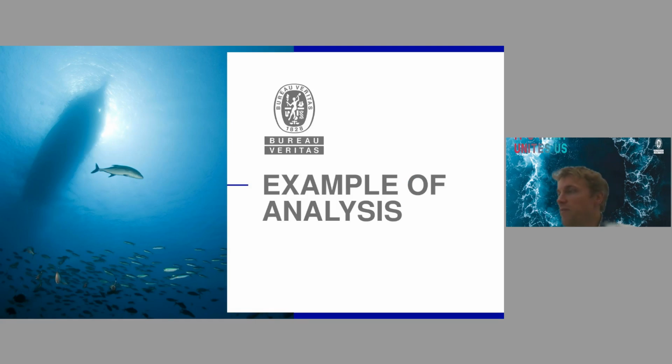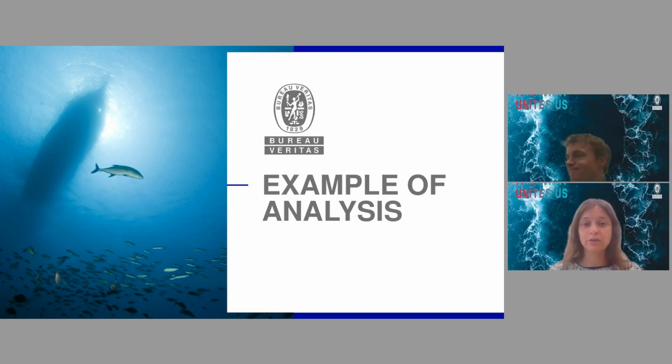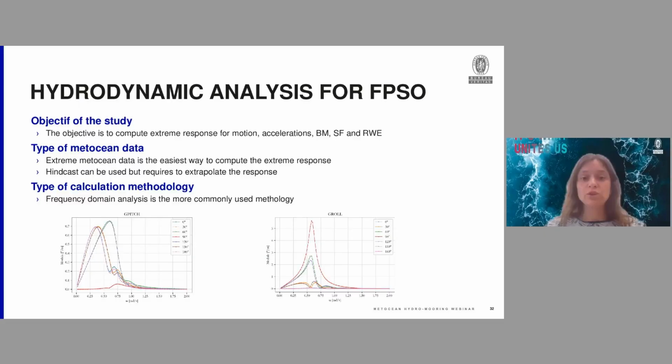And I will give back the floor to Claire-Julie to provide some examples of analysis. Thank you, Guillaume. So to sum up, some examples of really simple analyses to see how to do it. For example, a hydrodynamic analysis for an FPSO. The objective of the study will be to compute the extreme response for motion, acceleration, bending moment, shear forces, relative wave elevation for different load cases of this FPSO.